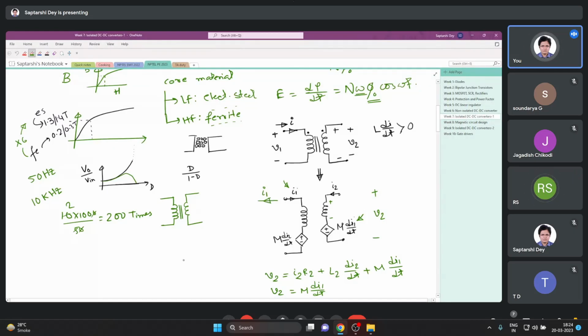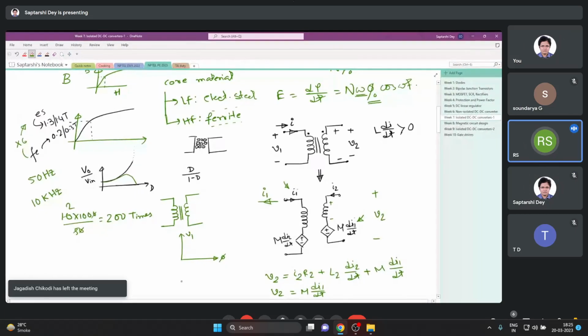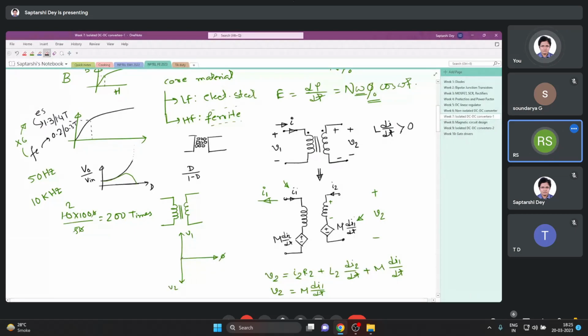That is what happens in an ideal transformer. If you have the flux here, voltage here V1, then this is V2, then the primary current is along this flux because that is what is creating the flux. The secondary current for a pure resistive load is in phase with V2. Then we refer it to the primary and add them. That is the total component. No, I am doing something wrong. I mu and I W will be there. No, I1 is the primary, sorry. We are considering ideal, so there is no core loss component of the current.